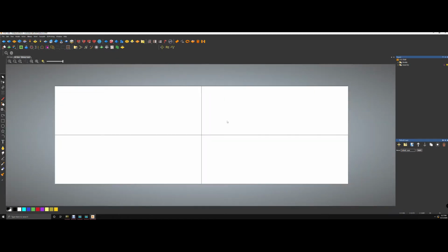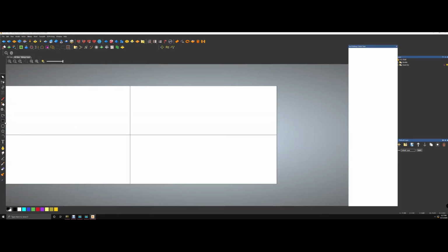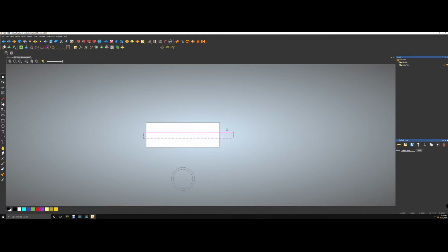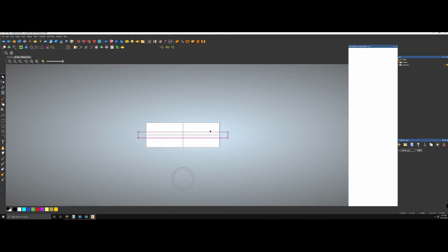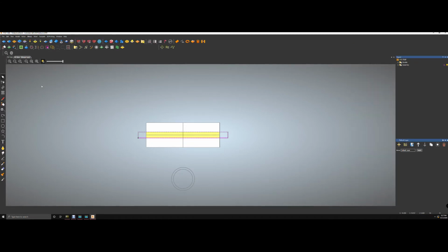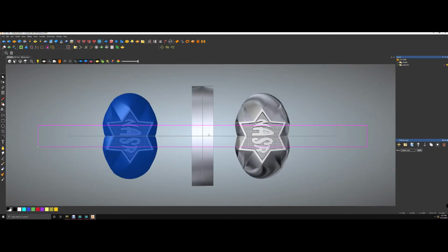Okay, so let's create just a simple ring by clicking a box here. We're going to go outside. Doesn't matter the width. F9 to center. F12 to bring the shape editor. And we're going to give this a 2 millimeter height. This is just for the demo. Okay, and apply and cancel. And we're going to look at what we just created.